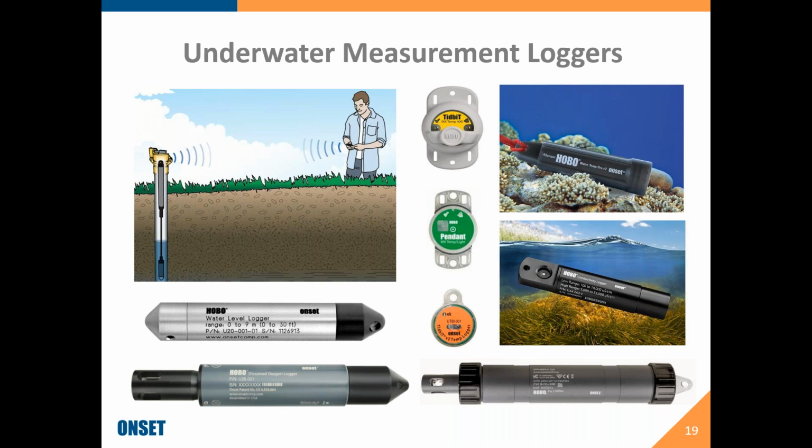The bottom right is a conductivity data logger. We also have a pH data logger. On the left is dissolved oxygen and a standalone water level logger. Now, as you can see, we've got lots of varieties, and it is based on your particular application. All of these are going to give you that time, date, and historical data.